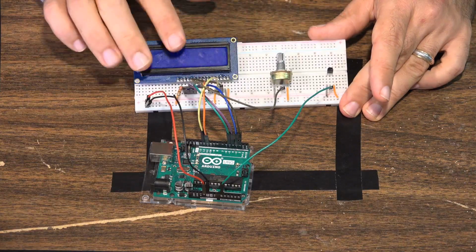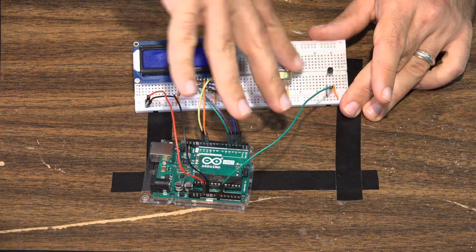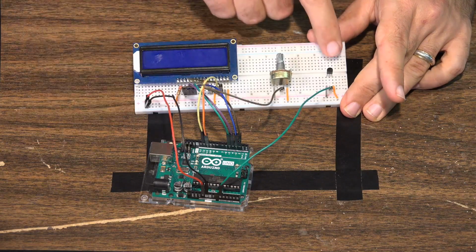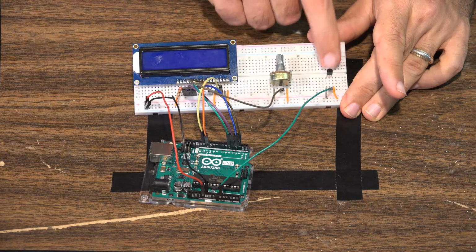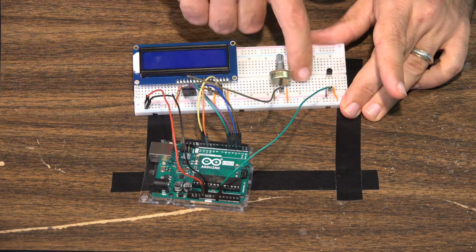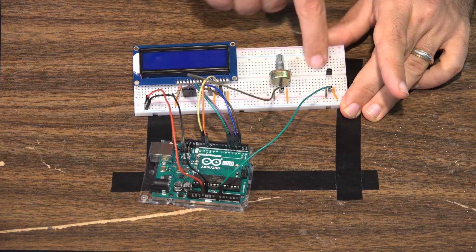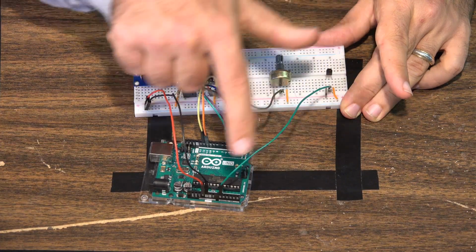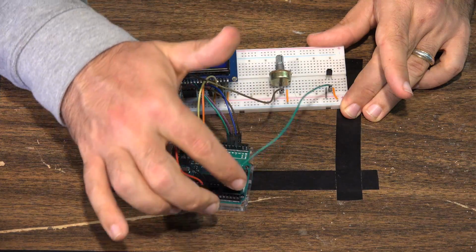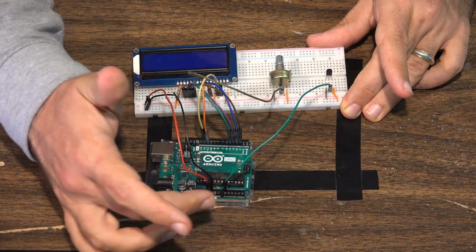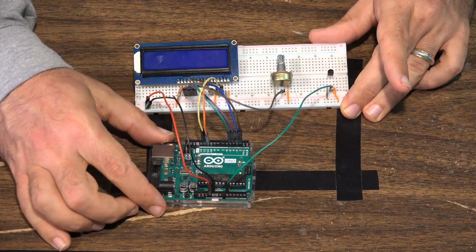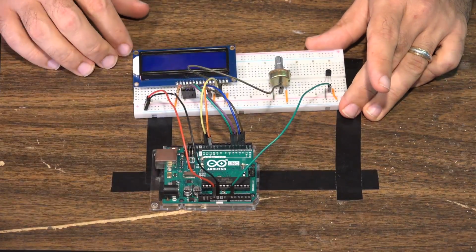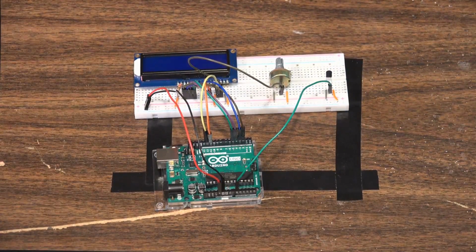But basically all we have here is the standard LCD screen project, and then what we've added is the analog temperature sensor down here. Again, we have the positive, we have the negative, and then we have the sensor pin, and that's an analog. Again, the analog sensor pin goes to the analog pins. It goes over to A0 on the Arduino board, and so this is what the project looks like when it's built. Let's go over and take a look at the code.